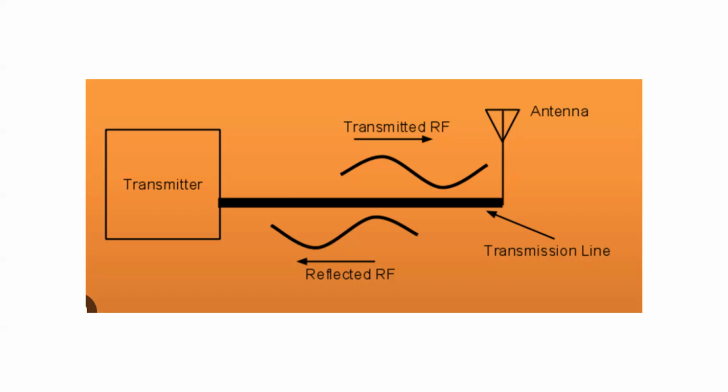The 2-to-1 is significant because most transmitters will start reducing the power if the SWR is over 2-to-1. But there's a device which we've talked about before called an antenna tuner that could be added to this diagram. And that way, if your SWR with your antenna system is above 2-to-1, it could transform it to 50 ohms and your transmitter will be happy.